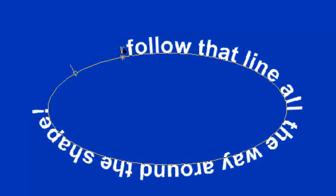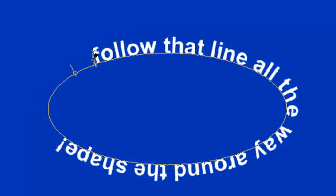And you can see how the text is following the outline of the shape that we've previously drawn. Automatically it goes to the outside, but if we hold down the Control or Command key, you'll see how our mouse icon changes, and we can click and drag inside to have the text follow the inside of the shape. We can also choose to move the start point.